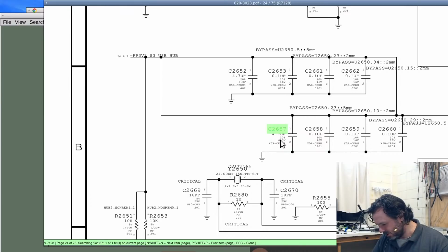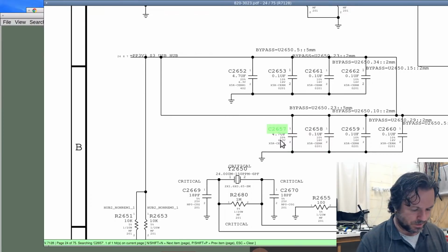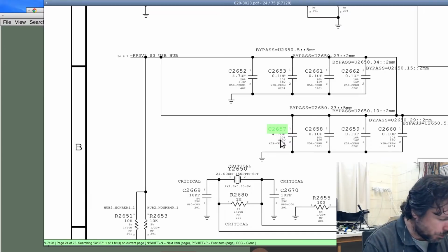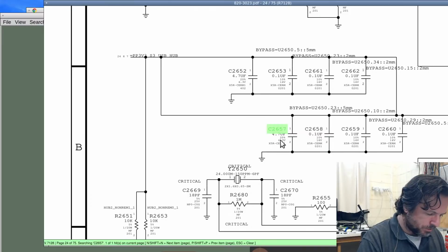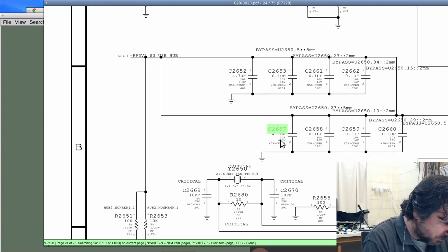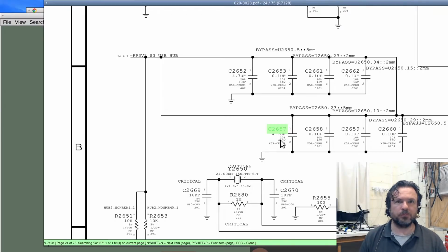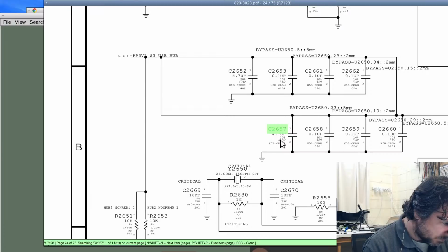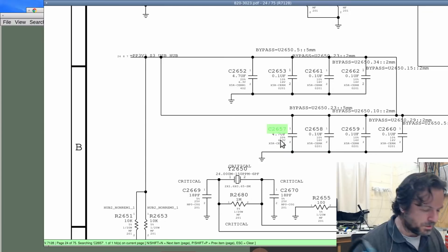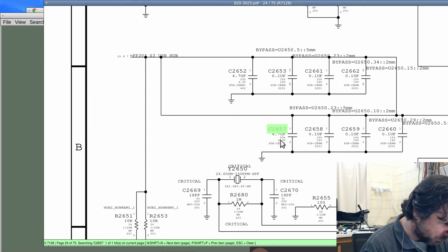In these sort of scenarios where it's not a critical capacitor, as in it doesn't really matter, you can just put whatever, pick another voltage, as long as you've got the right capacitance and you're over the minimum voltage required. If it saves you having to have a dedicated reel for that one value, then often it's just easy to do it that way. Drop in another one of a higher voltage. Because if you can save 1 second on the loading of a single part, that's a lot of time saved at the factory building the boards. So that's why they do that.